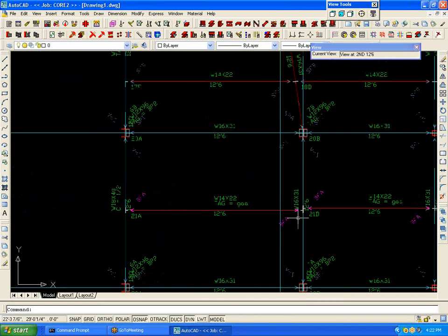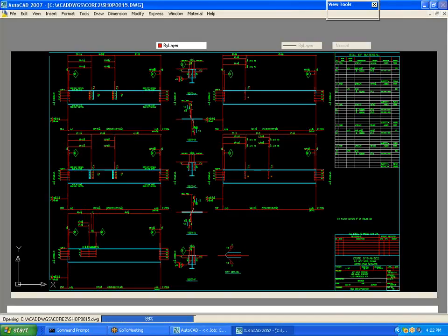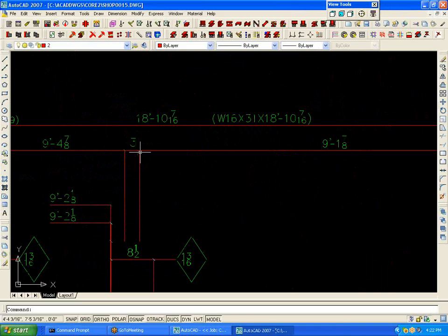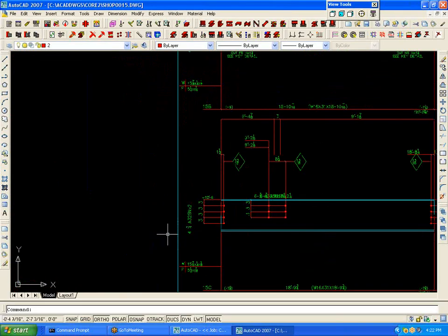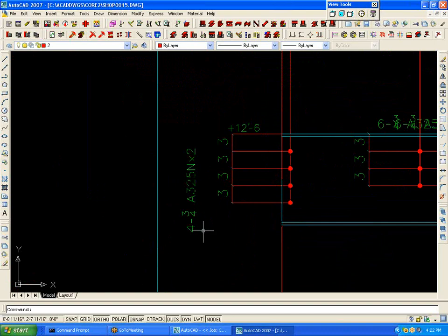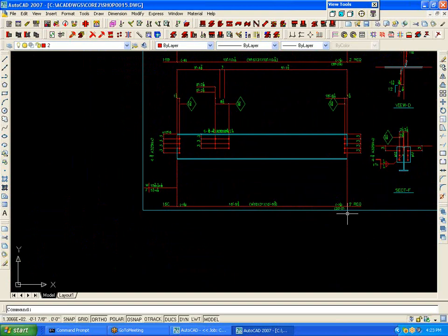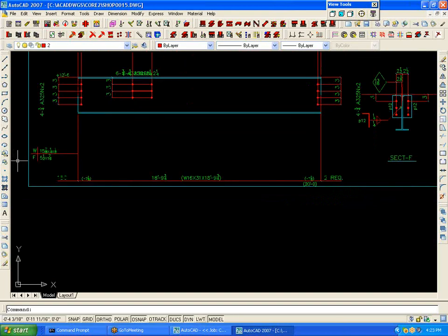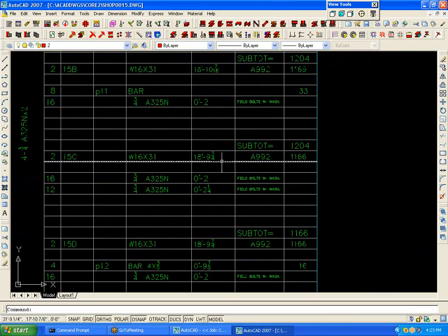So let's take a look at this beam 1631. That's piece mark 15C. So we click on it. And there's the 3-inch difference between the beams. There's the extension dimensions for the checker. Extension dimensions are for the shop, the out-to-out for the checker. The bolts are listed on the end of the material. There's a little scrubbing you got to do. There's the point-to-point, the minus dimensions, which gives you your final length, which will be the same length you find in the bill of material.